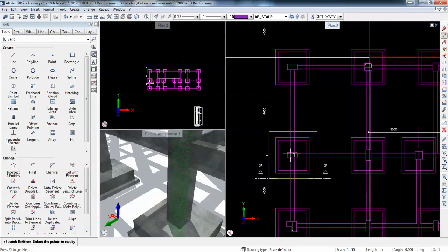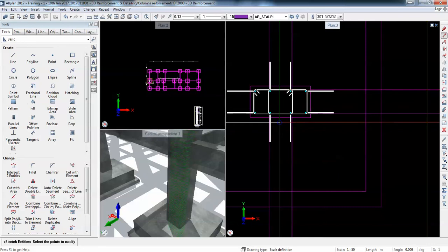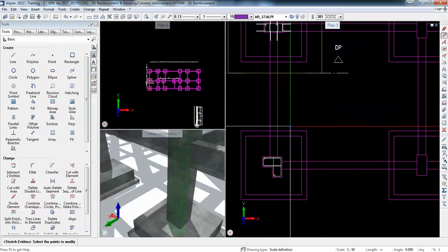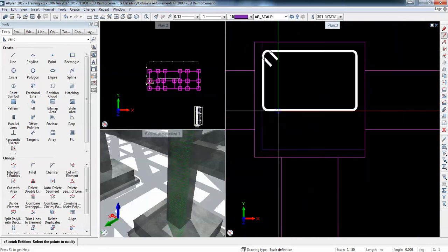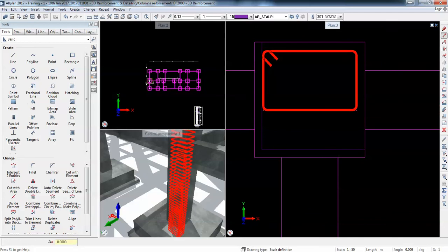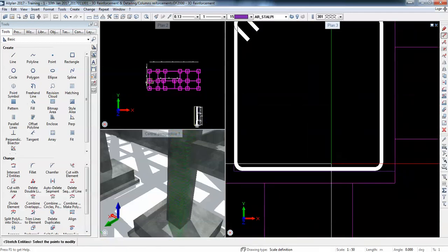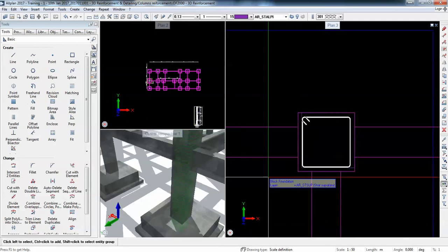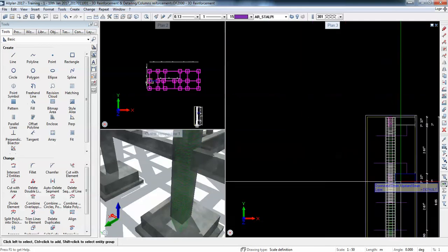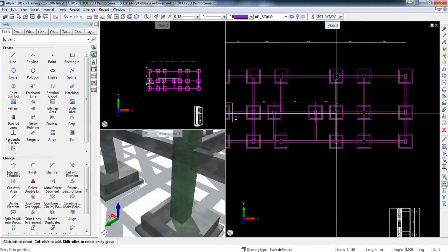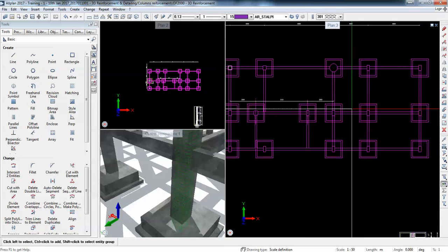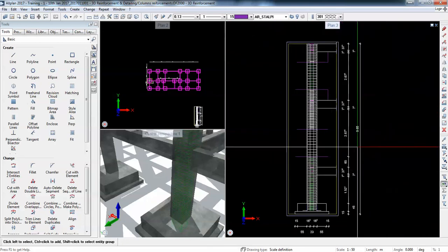And the trick is, if you take a placed reinforcement and start changing it, only what you're working on changes and gets a new rebar. You see that this one is not affected. So I use that same stirrup. Once I change it, it will automatically get a new rebar. So this helps a lot in productivity, as we only have to do the exact placement once and then just change. If any particular beams it's just in one situation, we just do this parametric change.